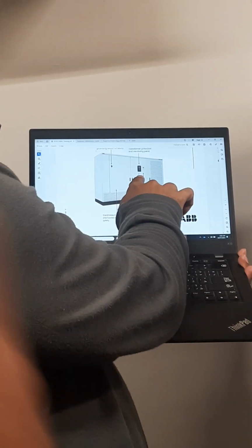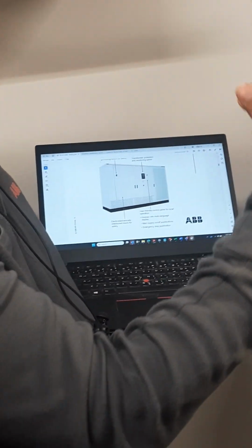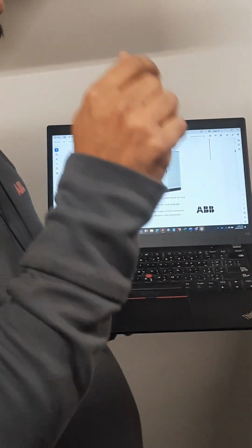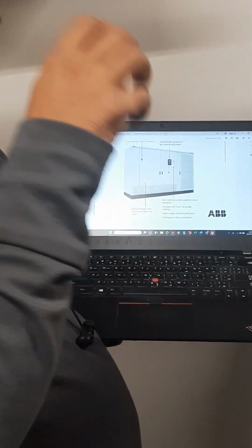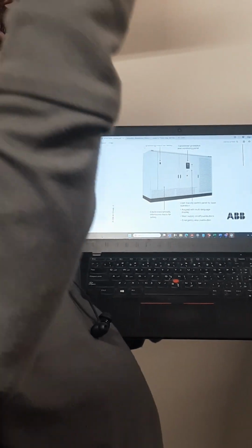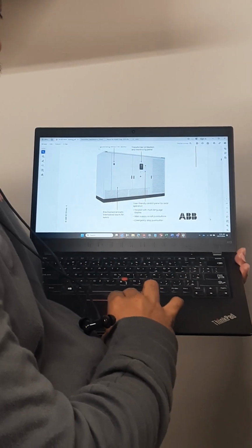There is an indicator, yellow. Yes, the ground. Okay, fine. Only when it is high can you operate this switch. Otherwise, you don't operate, because if you operate it wrongly, the isolator will get stuck. So that is another reason.